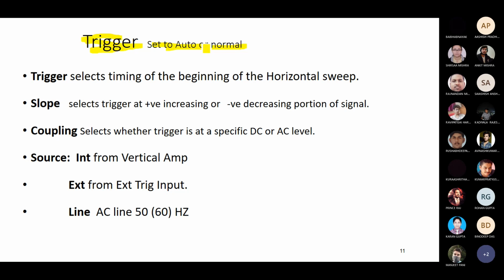Normally we take the response in the time domain, but in an oscilloscope we are able to take both responses. You can use one channel for voltage measurement and another channel for current measurement. Voltage is measured in terms of time, and current in terms of time. But it is also possible to measure voltage in terms of current and vice versa. For that you have to select one mode, called XY mode. Then your oscilloscope measures only the state variables.